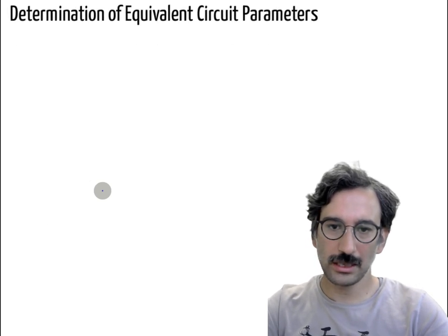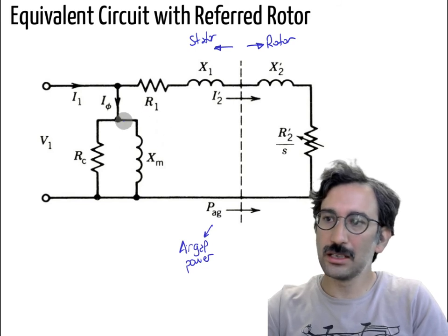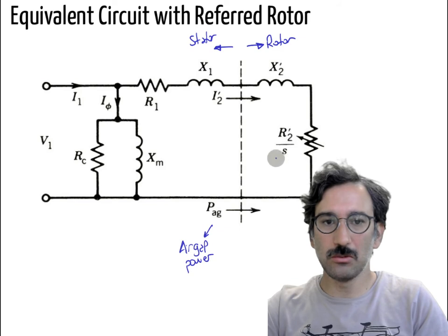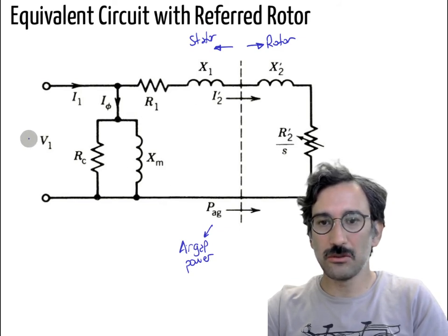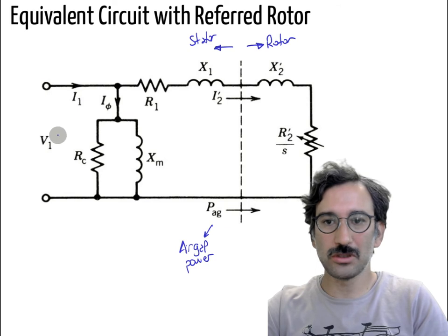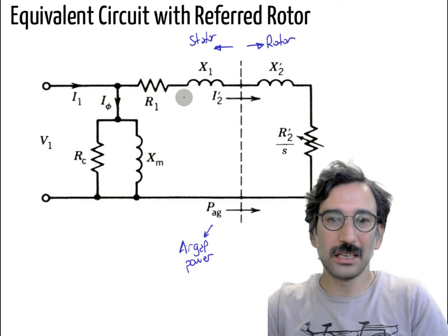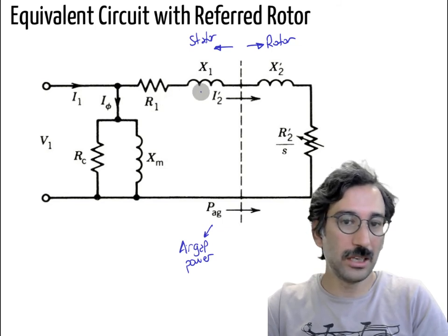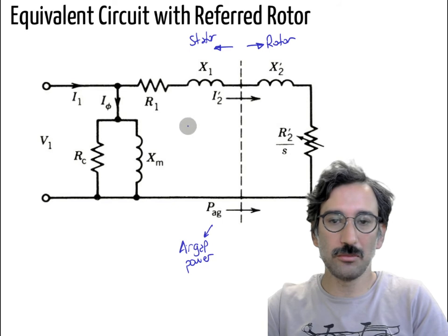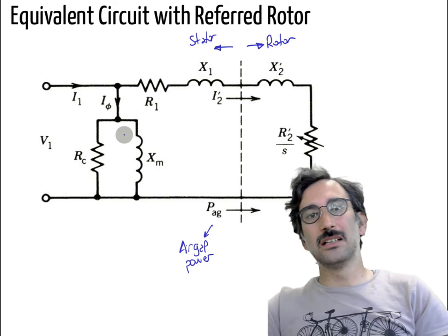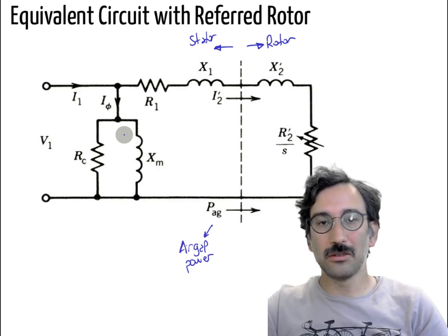So what happens? Let's go back again. This was our equivalent circuit, and in the locked-rotor test, s is equal to 1. You are applying a really small voltage, 10% of your rated voltage, for example. Then the parallel branch currents become really small. The series circuit components may be a couple of ohms or milliohms, but the parallel circuit components are usually in the kilo ohms range, or maybe 100 ohms.